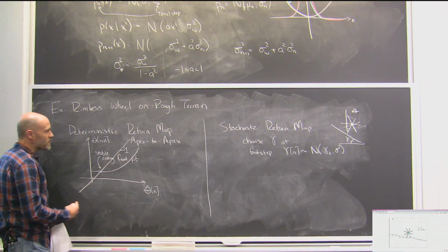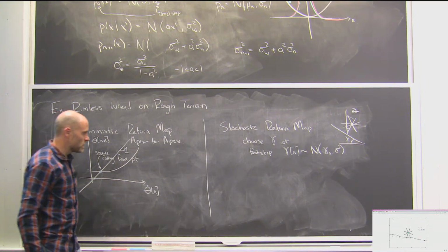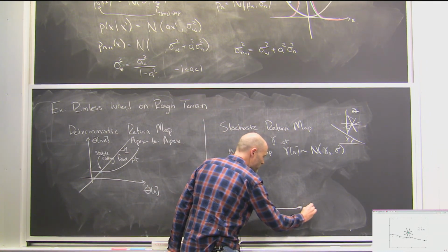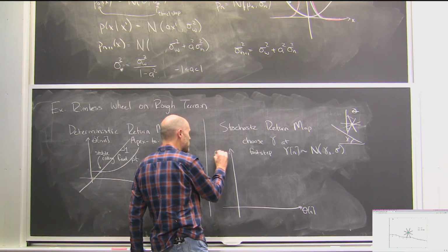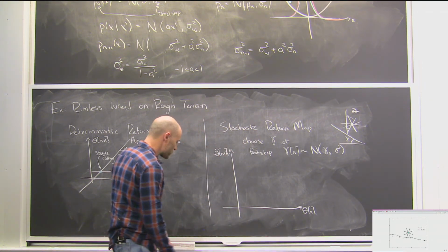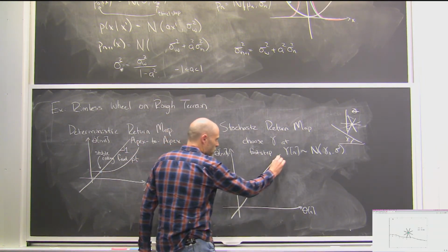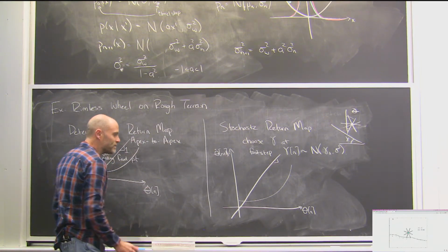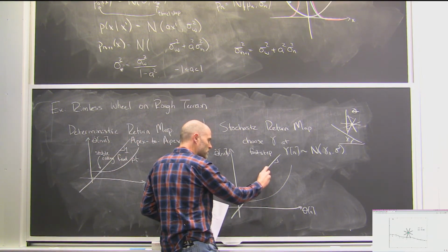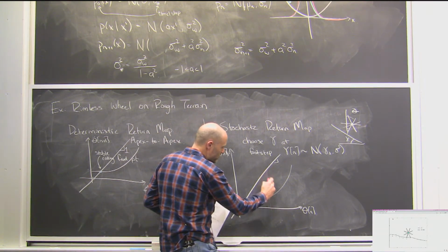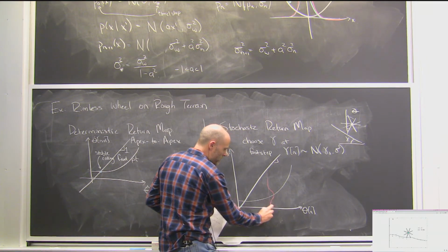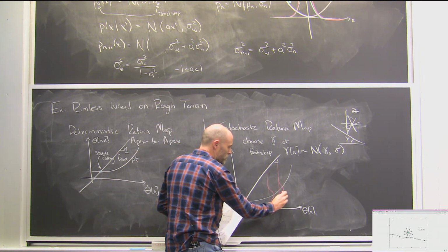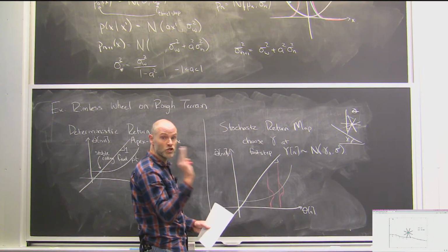Okay? Now what does that do to the return map? Right now, our return map is a stochastic process. So you can plot it in various interesting ways. But if you think of it as, I have my nominal return map, for any given theta dot, since there's some draw, there's some distribution of possible outcomes of the next theta dot. For any given thing, I've got a distribution that looks something like this, right? It's not exactly a Gaussian, it's a Gaussian shoved through the rimless wheel mechanics.